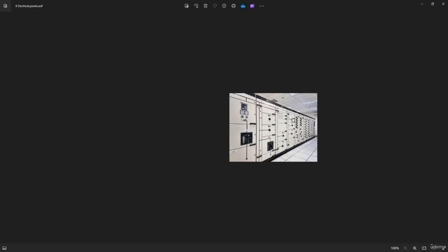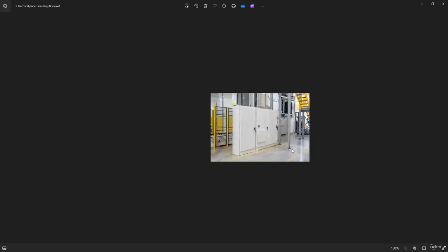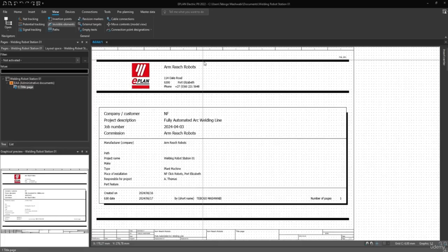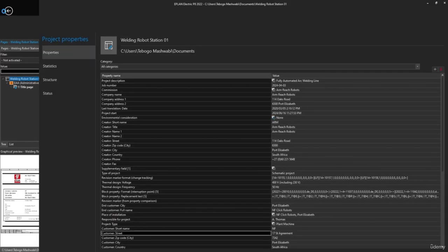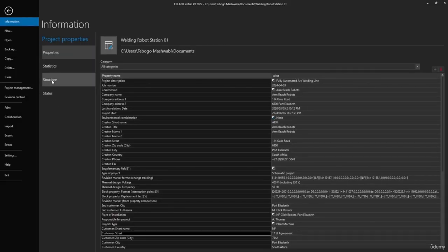So from #04, this is where we'll get power, and the power will travel from here by 200 meters onto a panel that's located near our installation site, which is near our station 05. So from station 05, then we'll feed our various devices, which are field devices, and also feed certain necessary enclosures. And on EPLAN, we'll just click on the project and we'll go to File and we'll start creating our structure.